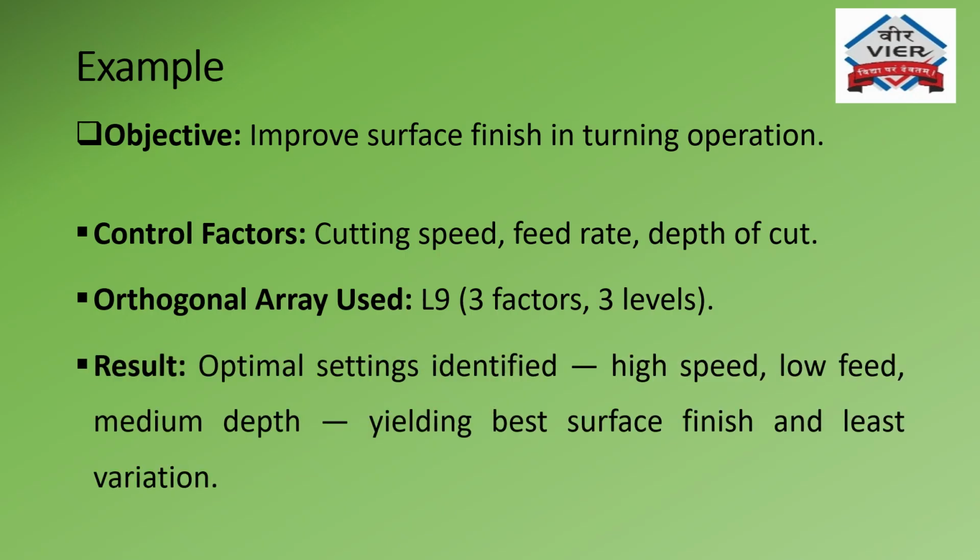By carrying out this orthogonal array, the optimal settings we identified were that by keeping high speed, low feed, and medium depth, the best surface finish can be achieved. So this is a simple example of the Taguchi method.